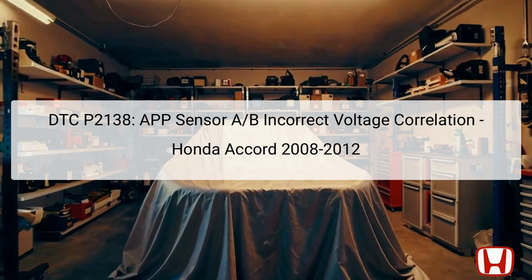The Diagnostic Trouble Code DTC P2138 specifically indicates a discrepancy in voltage readings from the accelerator pedal position APP sensor A and B. This issue occurs in the 2008 to 2012 Honda Accord models, which utilize the APP sensors to relay the position of the accelerator pedal to the engine control module, ECM, or powertrain control module, PCM.